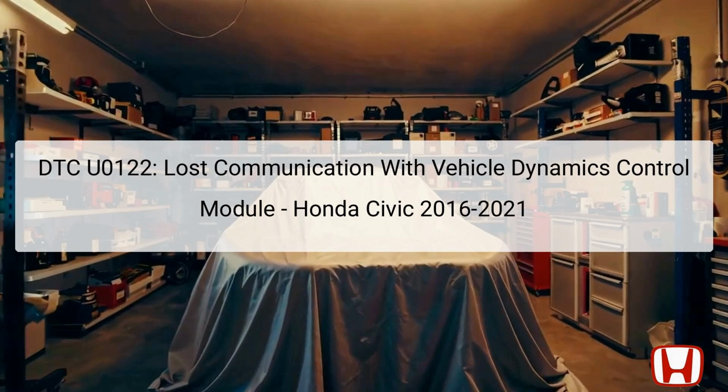DTC U0122 indicates a communication failure between the Transmission Control Module, TCM, and the Vehicle Stability Assist, VSA Modulator Control Unit. This error can arise from issues in the Controller Area Network, or CAN, responsible for transmitting signals among various vehicle modules. The two signal lines in the CAN are FCAN high and FCAN low, which facilitate real-time communication between control units. When the TCM does not receive proper signals from the VSA modulator control unit for 1.5 seconds or detects abnormal information continuously, it records this error.